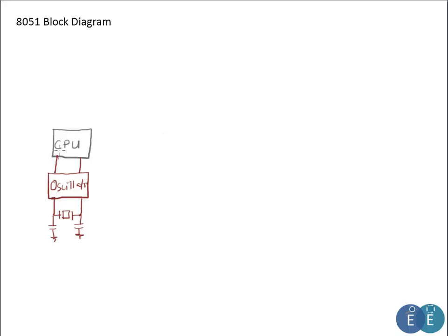So it's just a simple oscillator that we have in this case. Now, since the CPU requires some kind of temporary storage, we have something called registers. So these are temporary storage units, which are again 8 or 16 bit, and they help the CPU to keep the data for basic operations. They could be arithmetic or logical operations.